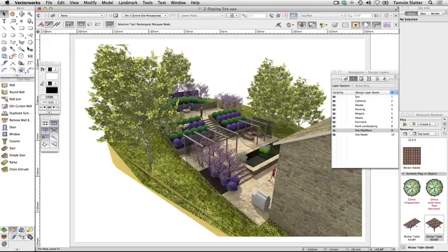tools work. However, in reality, most landscapes are not flat, nor do they fall neatly into distinct flat planes at different levels. How does Vectorworks handle sites that slope, and how can you represent these slopes in your model? Well, Vectorworks includes a very powerful suite of tools for creating and editing site models. You can use a site model to represent the existing site and then use a series of site modifier tools to apply your design changes to the site and even calculate the cut and fill volumes resulting from your changes.